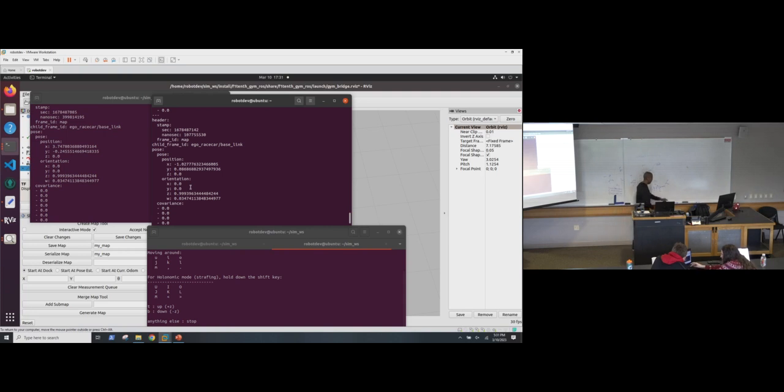But the beauty of a quaternion is, again, it's usually called Q or Q dot. In MATLAB it's a vector like this: W, X, Y, and Z. If you do the sum square of W squared plus X squared plus Y squared plus Z squared, it has to be equal to 1. That is the condition.